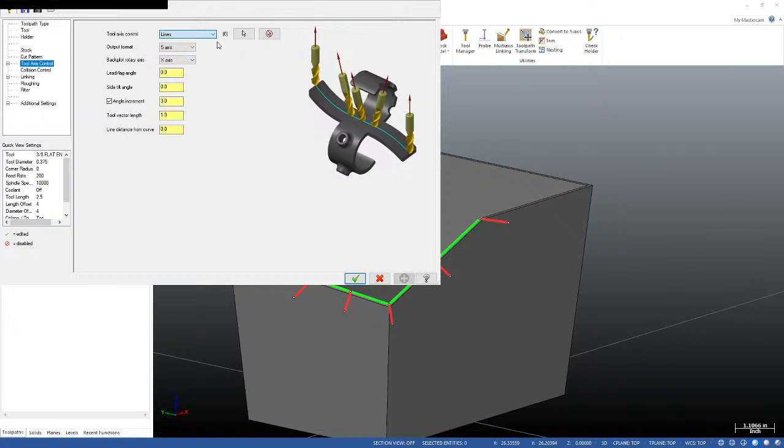In terms of the curve 5 axis, we've got these 6 different options for telling Mastercam how I want my tool orientation to be as I'm making the cut. Probably the most common method by far, and the method that I typically use for trimming, is lines, followed closely by surface.